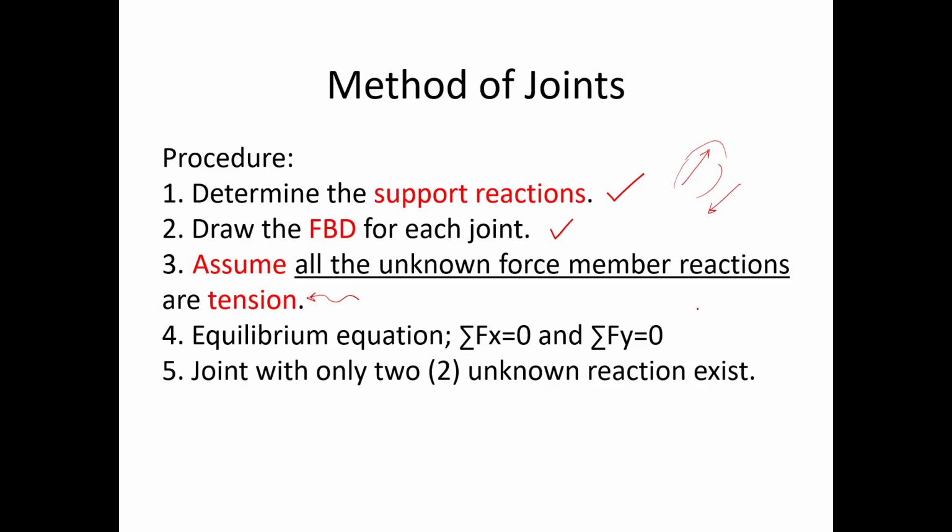Okay, so the equilibrium equations for the joint system, or the method of joints, are just the summation of forces in x equals 0 and the summation of forces in y equals 0. The summation of moments equals 0 will be used to determine the reaction forces.